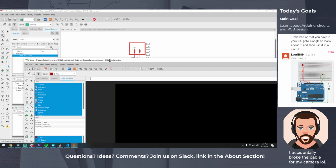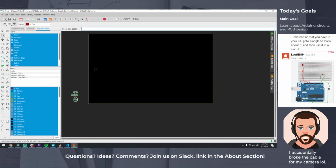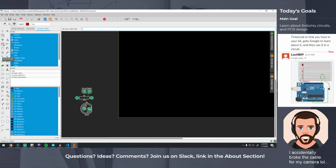So what we get is this new window where this black box is our entire circuit board. So it's very big, see, relative to our components down here. So we'll want to resize this after we drag in our components and get them positioned nicely. So we'll come in here with our move tool. Again, we have to grab the center. So this time it's the yellow plus. And we'll drag this into the area of where the circuit board is.